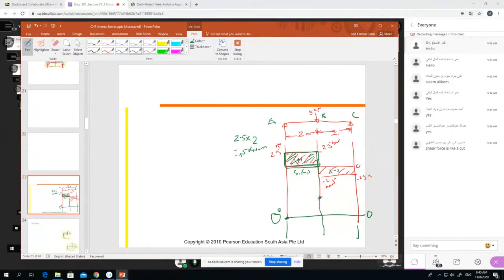Here is the 2.5, and we have to draw it as an incline. If it is straight like this, you will draw the incline. Then we have plus 5 here, and when we come to this point, our bending moment value will be minus 2.5 into 2, so equal to 0. So it's 0, and we connect it like this. So the bending moment diagram, BMD, is this. So yesterday we drew it like this.